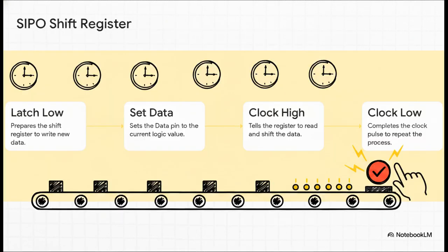To visualize this, think of the clock pin, or CLK, as a constantly moving conveyor belt. The data pin, the SDI, is the actual package of ones and zeros being placed onto that belt. And the latch pin, or LAT, is the supervisor. So the clock pulses, moving data down the line one step at a time. Once all the data is perfectly lined up in the register for that specific section of LEDs, the latch supervisor hits a button, dropping all those packages into their respective LEDs at the exact same fraction of a millisecond. It's totally brilliant, allowing precise control of multiple LEDs with minimal wiring.